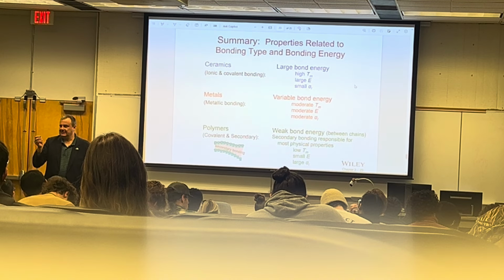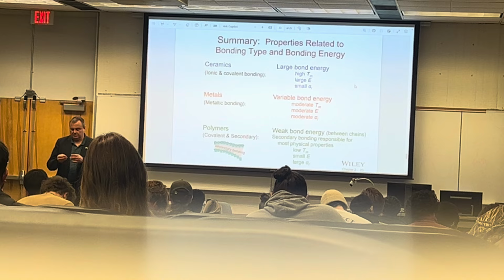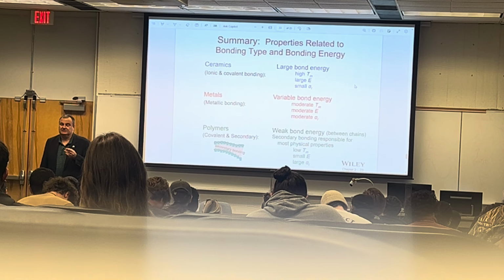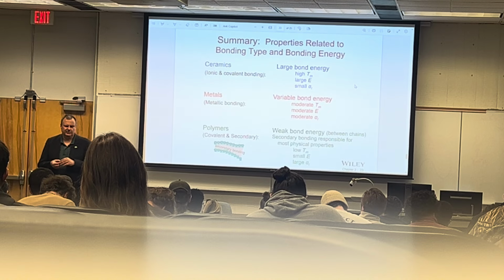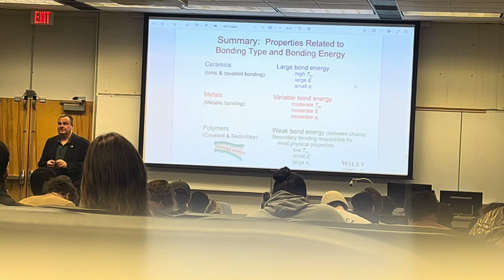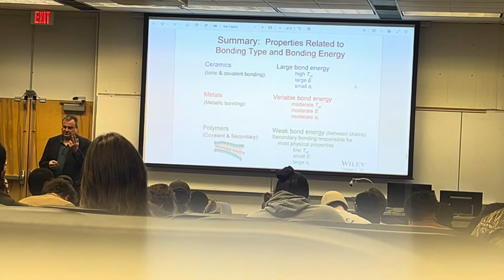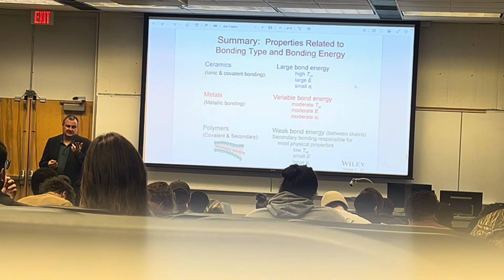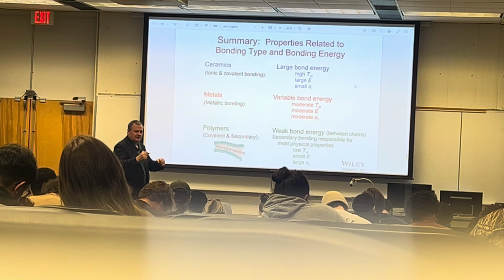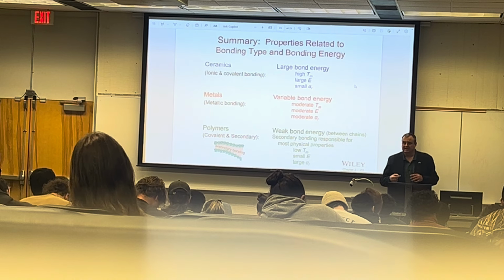And even though each individual LED, a component of this, is rated for 50,000 hours, which is 10 times more than a regular bulb, the system, which consists of so many components, is subject to the weakest link. There's even a show, the weakest link, right? Because the LEDs did not fail. Something else on this device failed. And for the incandescent bulb, how many pieces are there? Well, there's glass, and then there are metal contacts, which are in kind of vacuum or inert gas, and then there's a tungsten filament. So 3 components. Now, of course, it is subject to vibration because you're driving your car, it vibrates. You know, you only turn this on at night. You're not driving with your headlights on during the day unless it's automatic.